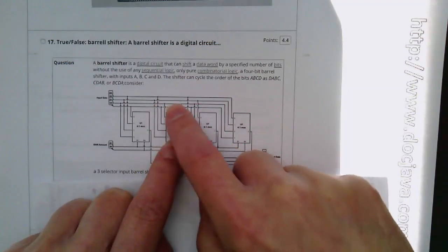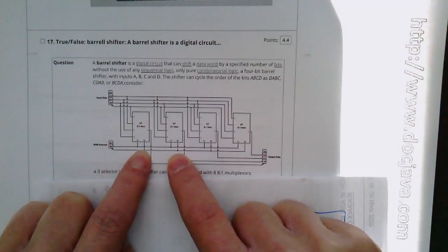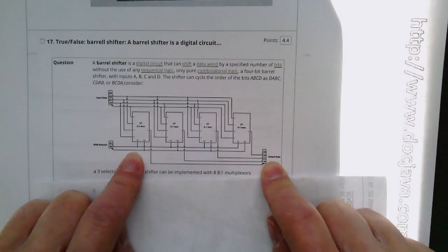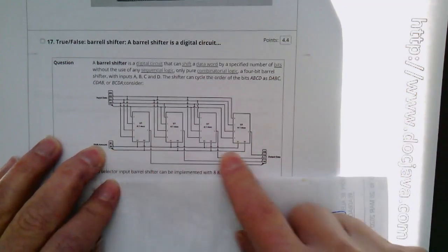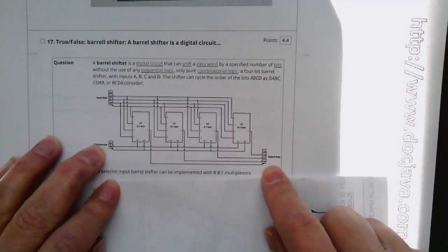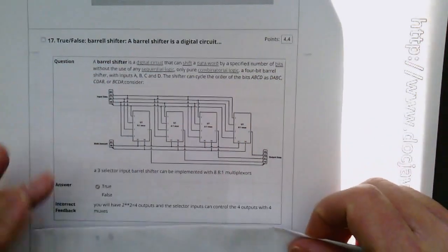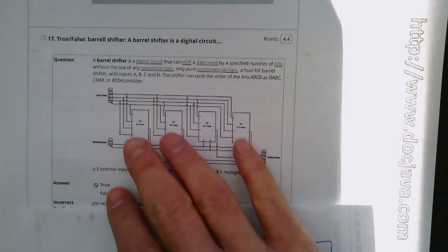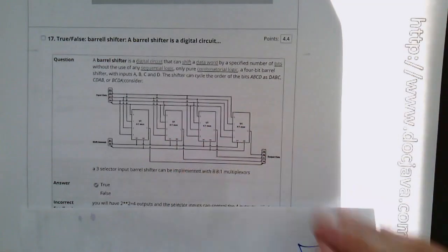And similarly, they're all wired differently, and so when you go through the permutations 0, 1, 2, and 3, you'll get different outputs as a result. And so you can effectively look at this by inspection and say, yes, this is all going to work in 3 gate delays. All you have to do is choose how you want to have the bits arranged, and then you can get that arrangement directly out from your 4-to-1 multiplexers. And so you've got an opportunity now to do an application of multiplexers to make a shifter and do it all in 3 gate delays, which is kind of cool, actually.